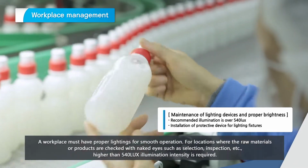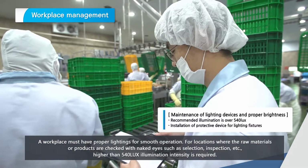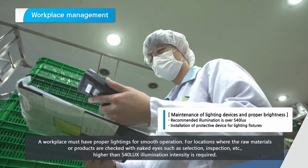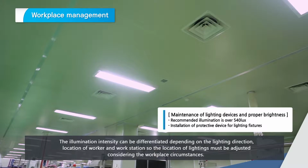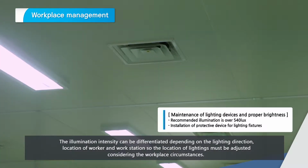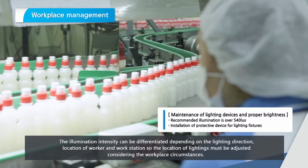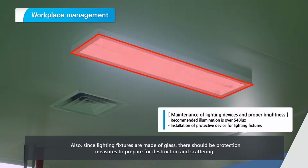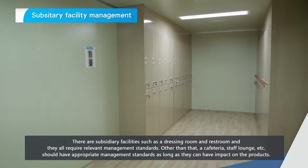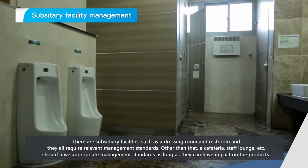For locations where the raw materials or products are checked with naked eyes, such as selection, inspection, etc., higher than 540 lux illumination intensity is required. The illumination intensity can be differentiated depending on the lighting direction, location of worker, and workstation, so the location of lightings must be adjusted considering the workplace circumstances. Also, since lighting fixtures are made of glass, there should be protection measures to prepare for destruction and scattering. There are subsidiary facilities, such as a dressing room and restroom, and they all require relevant management standards.